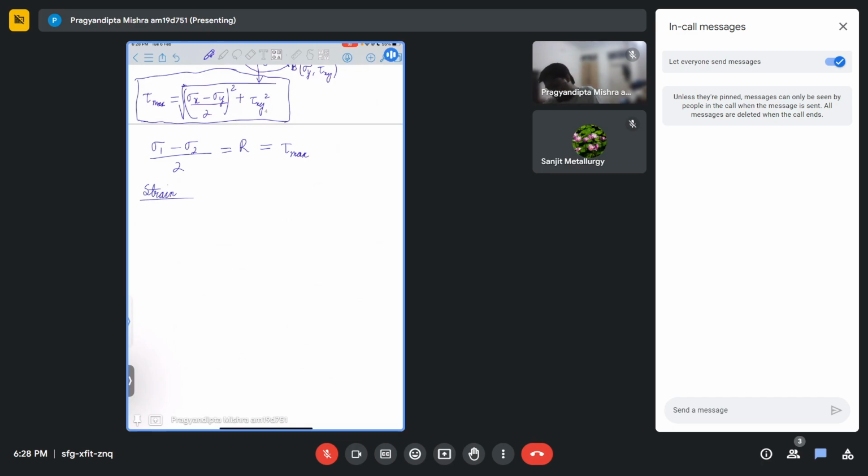Now we discussed strain in the last class, right? What exactly is strain? If you remember, strain is just a measure of deformation of a particular material. And just like stress, we can represent strain using both magnitude and direction. So it requires two entities. It is not enough to describe strain just like force, with just direction. You also need direction and the plane in which strain is acting. So it's also a tensor.